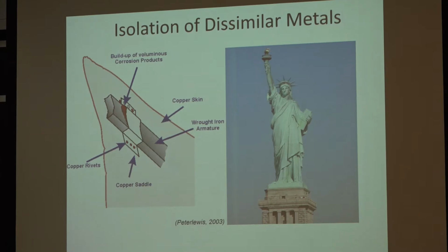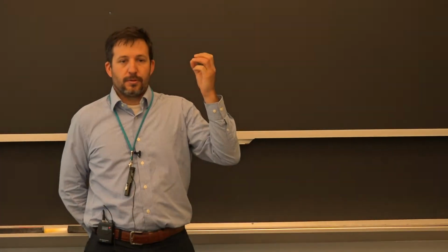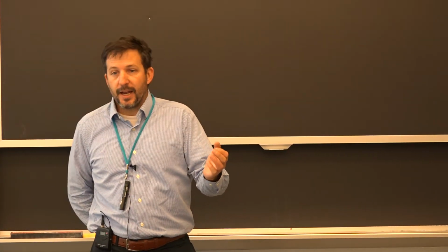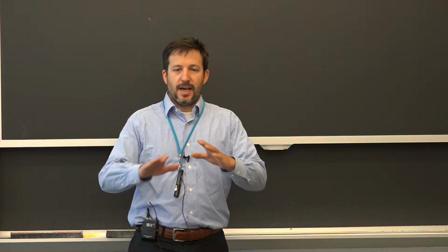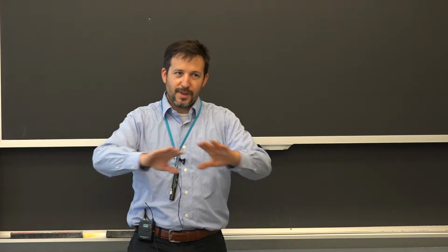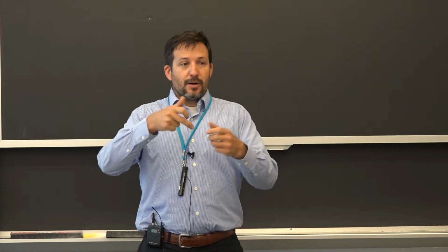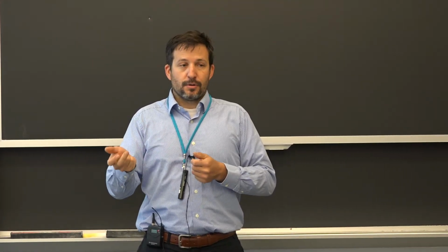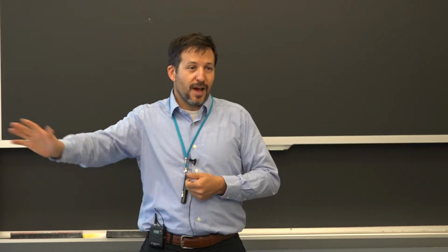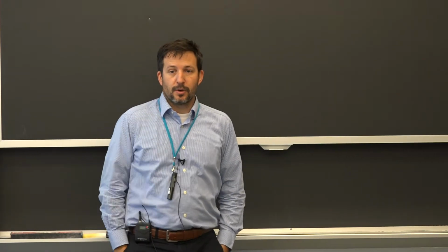Essentially, if you're going to have dissimilar metals, you would like the small part to be the one that is more resistant to corrosion. So an example of a roof, and that has been done before, is you have a copper roof and you use steel nails to lay it down. It's the worst that you can do because these small fasteners that you use are going to corrode instead of the copper flashing that's the main surface. So you'll lose your nails or bolts very quickly.